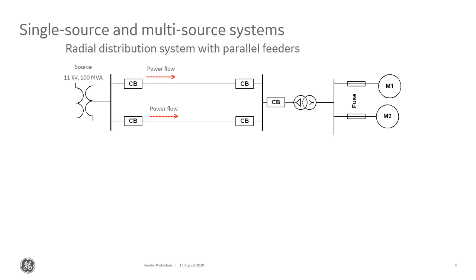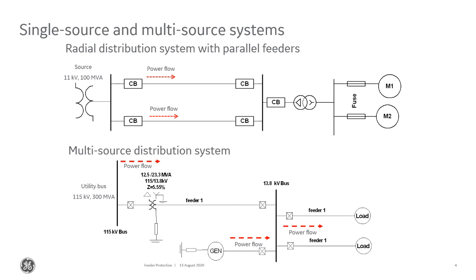That's the problem of having multiple sources, and in a transmission system that happens all the time, because every substation is a source, every connection on the transmission side is a source. So on the transmission end, we use different types of protection. Overcurrent protection by itself does not cut it. We need to use distance protection, differential protection and such to overcome the issue of current being able to flow in all directions.